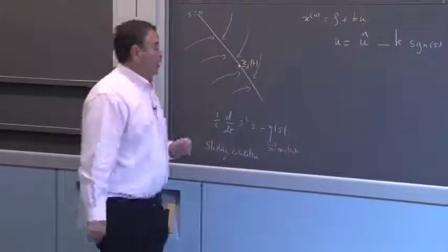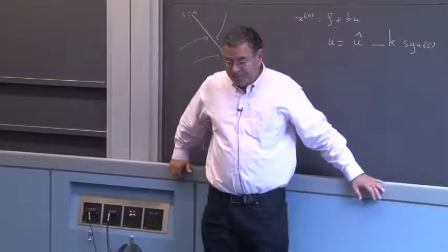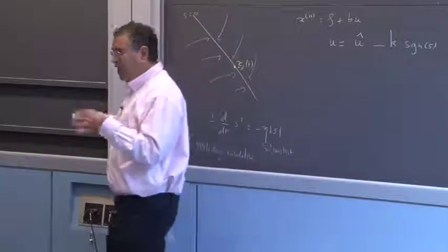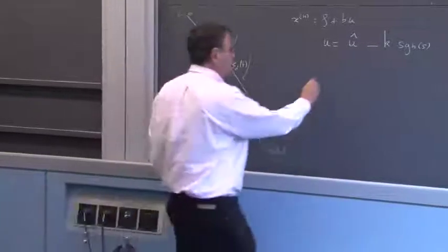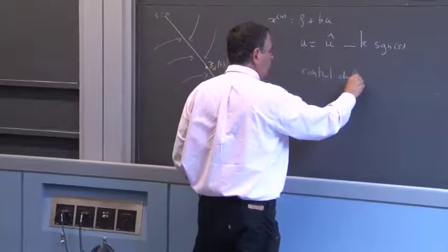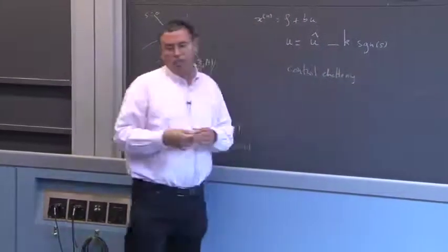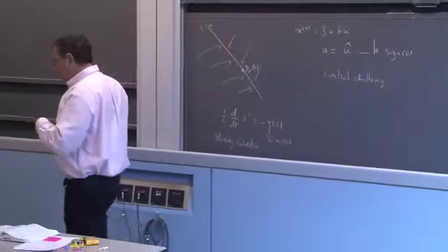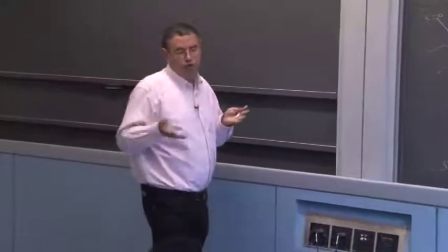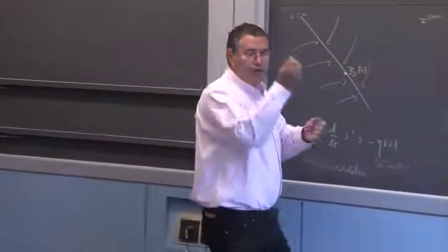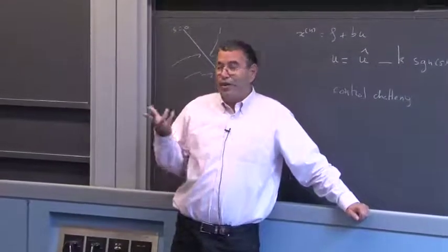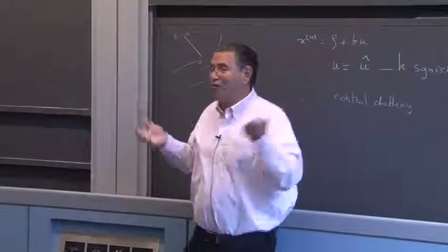It's fine in the sense that the controlled chattering it creates in practice is okay because we happen to be driving, for instance, an electrical motor through pulse width modulation, so the control signal is of a chattering nature anyway, and we might as well have it chatter the right way.